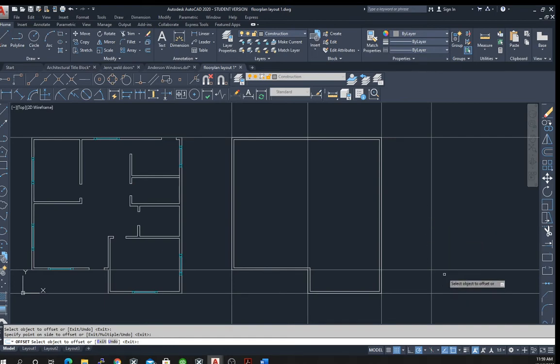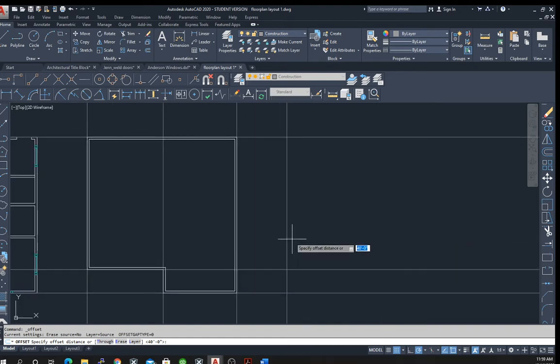Okay, so there's our construction line. So this would be at the start of our facade. Now, we know that the front facade, the width will be 30 feet. So we can put another line 30 feet to the right of this line. So again, we type 30 feet, enter, click on this line, put in that construction line.